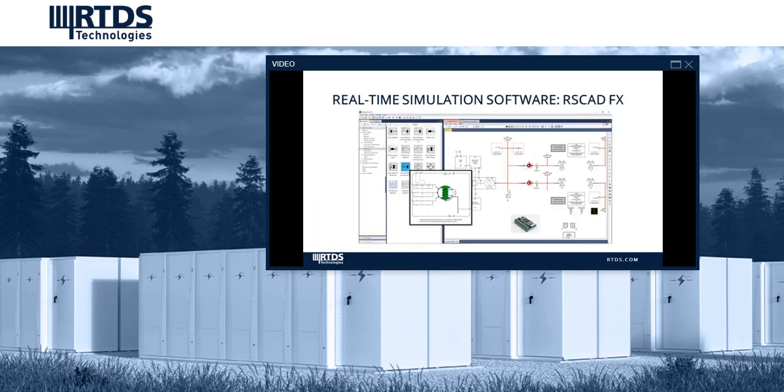Now that we've discussed the hardware interface, let's focus on the software aspect of the tool. RSCAD is our proprietary software, and it allows you to configure your circuit model and interact with the simulation. So here you can see the Draft module where the user builds their circuit and enters parameters into the models. You'll see it in much more detail in the demo, as well as the Runtime operator's console where the user can apply contingencies to the system and change parameters in real time.